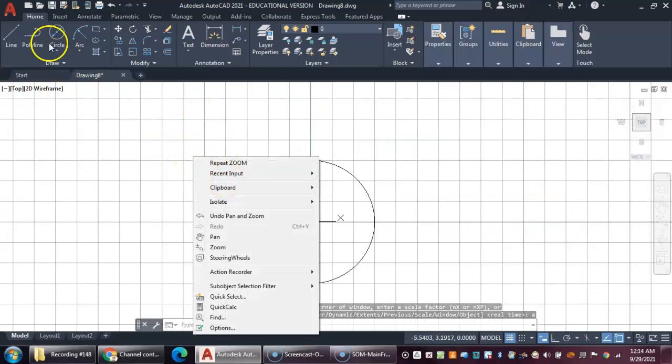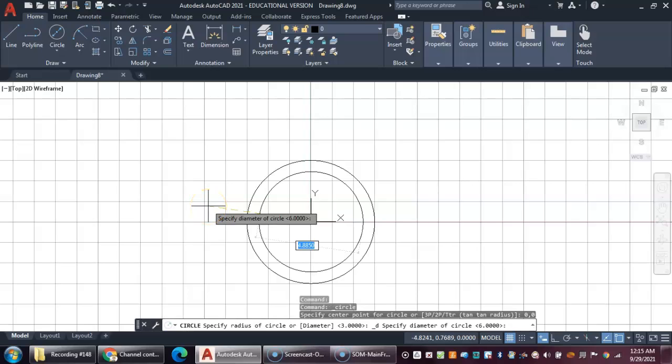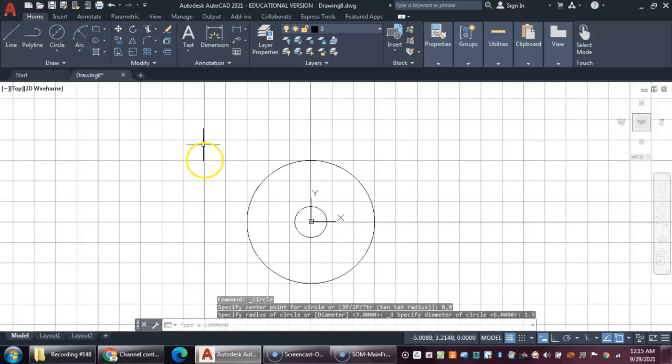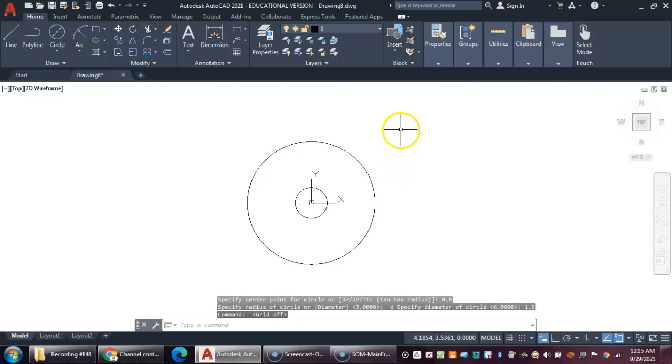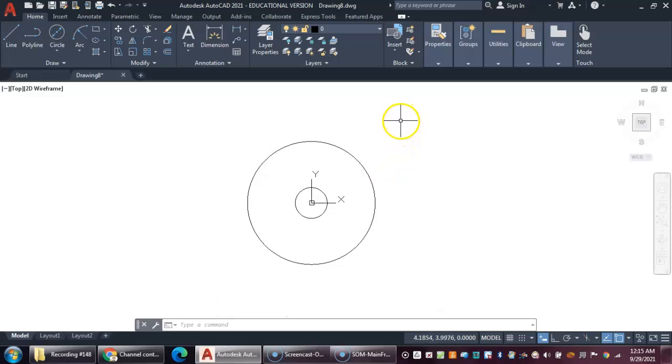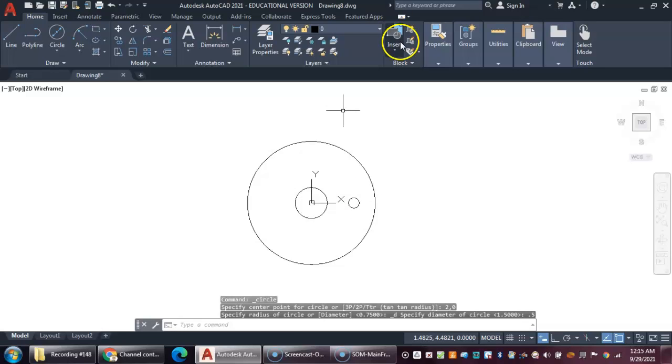We'll do the circle tool again. Here we can again type in 0,0, and the center diameter here is 1.5. So I've got that. Let me go ahead and get my grid off of here for right now. Then I have a 1/2 inch diameter circle that is over 2 inches in the X. That's a real simple coordinate point entry for the center, because I know that is going to be 2,0 as far as the points there. And again, this is going to be a 0.5 diameter instead.